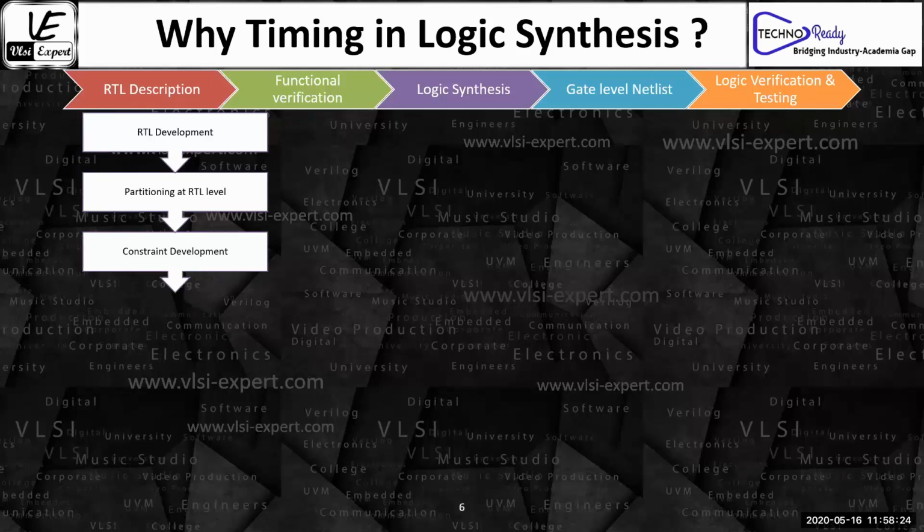If the top level person is doing the partitioning, they should have all these constraints. For example, on pin A you will get data at 0 nanosecond, on pin B you will get the data at 1 nanosecond. At least this information I should provide you. And the way, or the language, in which we provide this information is itself known as a constraint, because it becomes a constraint for your design.